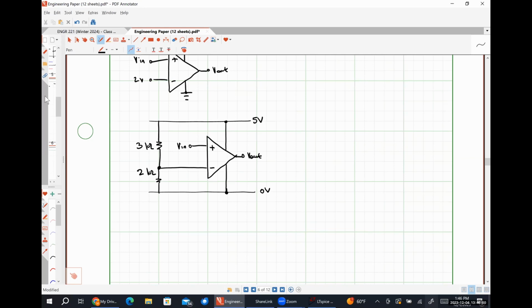That's going to put VX between this node and this node. It was originally between this node with terminal A and this node at the top left of the circuit, so it's still between those two nodes. So VX isn't really the voltage drop across the 10 ohm resistor, although it is; it's the potential difference between these two nodes. So it still needs to be between those two nodes if we were to do a source transformation.